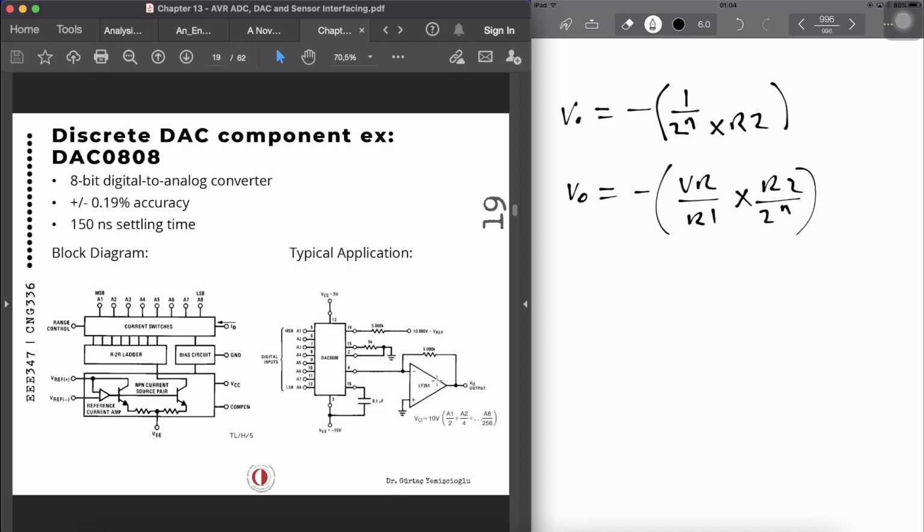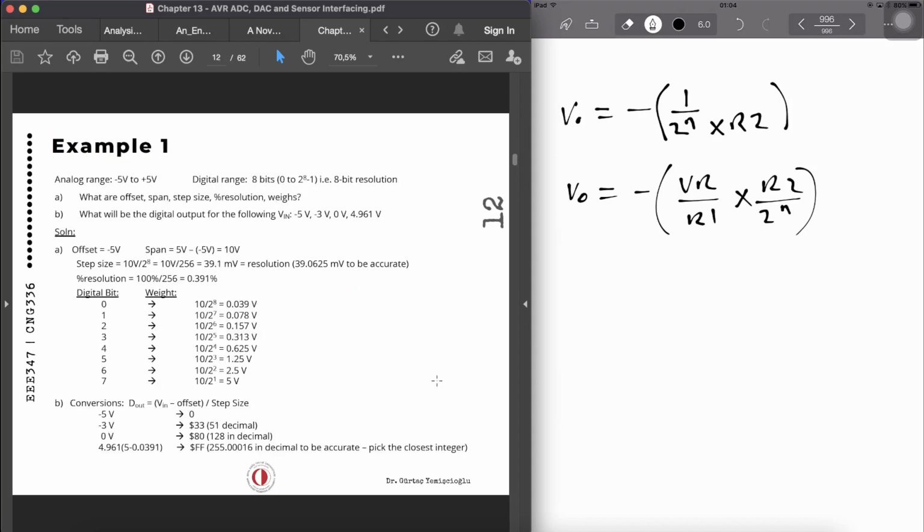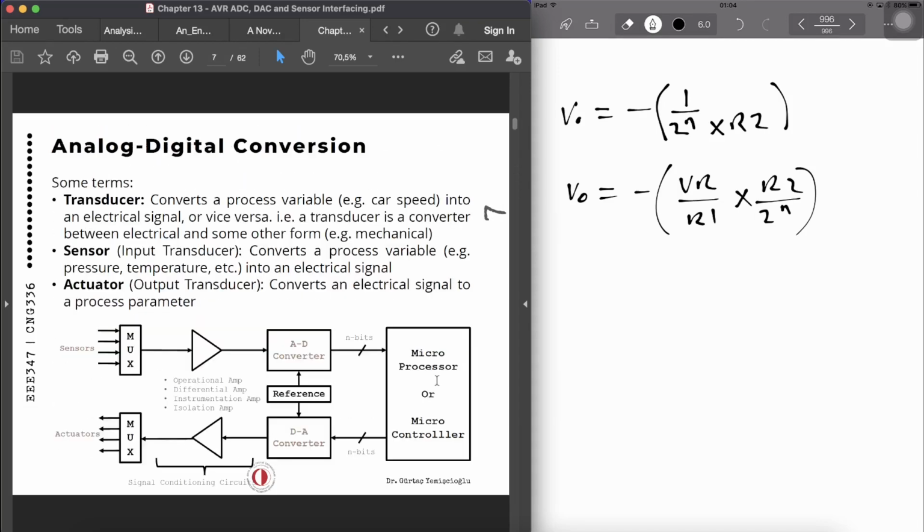Now, when we talk about this type of processing, what we have tried to show in slide 7 over here is that whenever we have a digital to analog converter, we may have some signal conditioning so that we can drive the actuator, because you might need this signal conditioning circuit to do some voltage manipulation, maybe voltage level shifting.